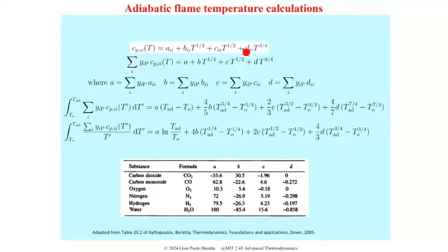And with that kind of correlation, you can do it simply by using a correlation with similar fractional powers of the temperature with the coefficients that are weighted sums of the individual coefficients of the various molecules, which you take from this. And then also the integral of these fractional powers of temperature can be done explicitly.